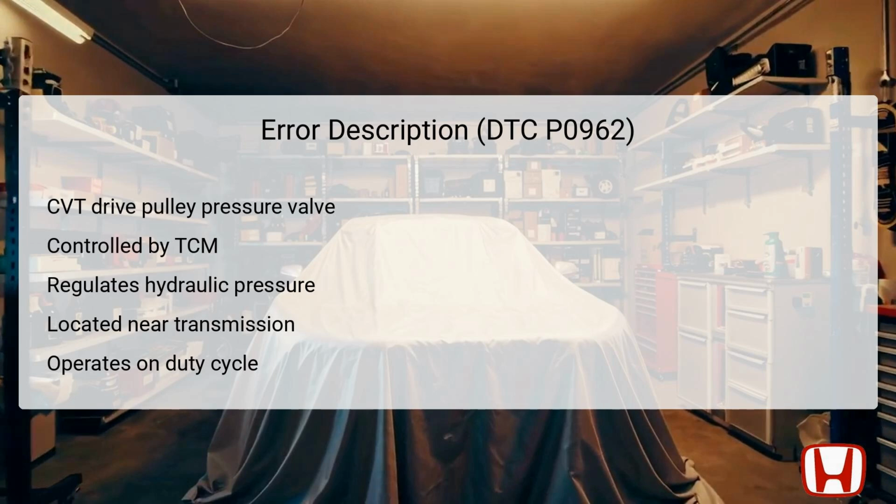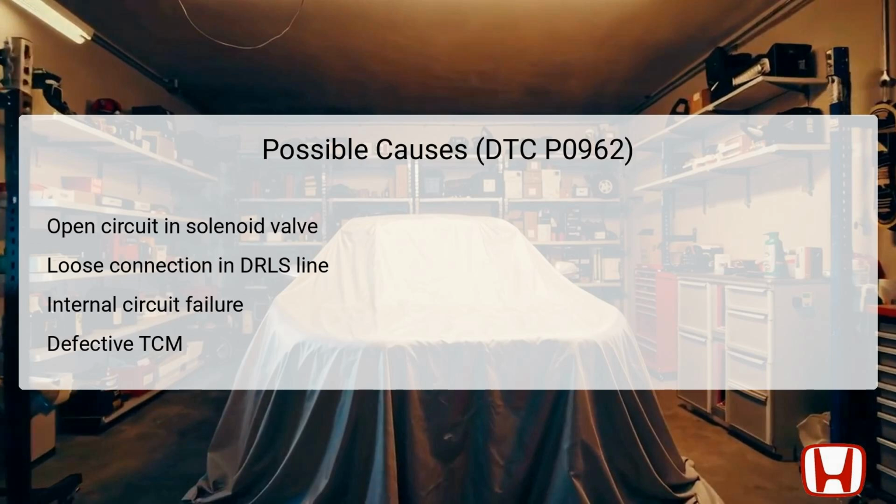hydraulic response. If the control valve fails due to an open circuit, whether from a loose connection or an internal malfunction, hydraulic pressure will not be correctly regulated. The end result is that the vehicle experiences performance issues that may lead to a DTC being raised and illuminated dashboard warning lights.